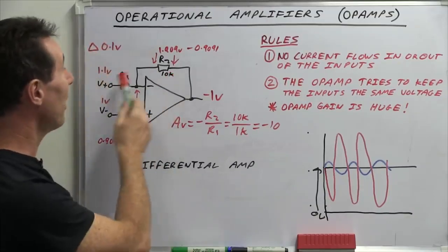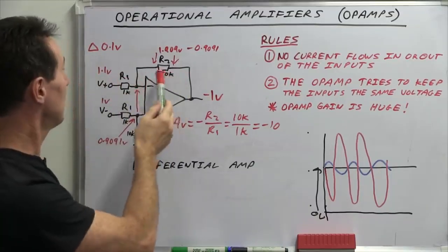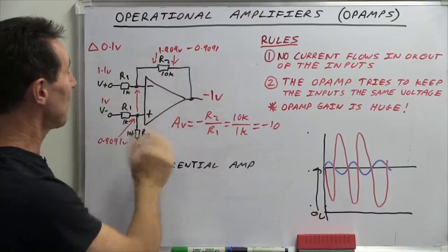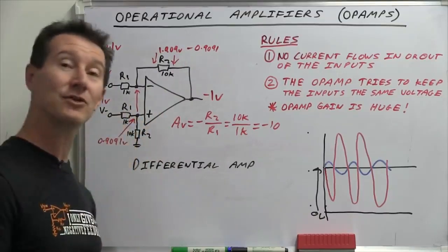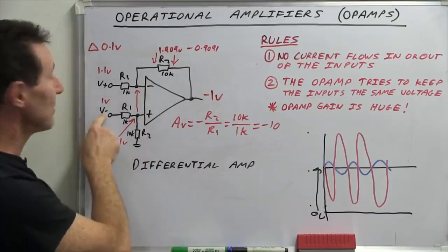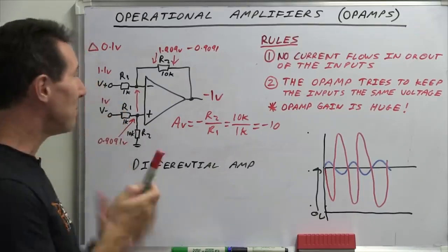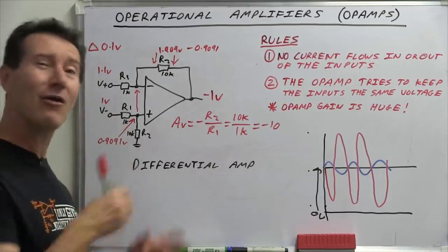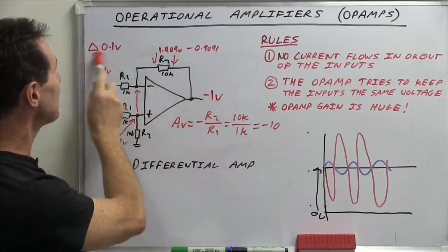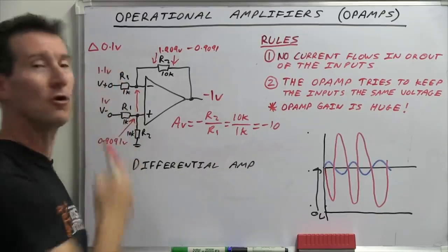But if you combine the inverting amplifier configuration that we just saw, so we've got the feedback going here, our signal going in, that's a standard inverting configuration, and we have exactly those two resistors that we saw before to bias that voltage up. But instead of going to the supply rail, we make that our other differential input, and bingo, it becomes a differential amplifier. I'll let you go through the actual calculation yourself to find out, but basically the difference that we're feeding in, if we're feeding in 1 volt into here and 1.1 volts into here, we have a difference of 0.1 volts.